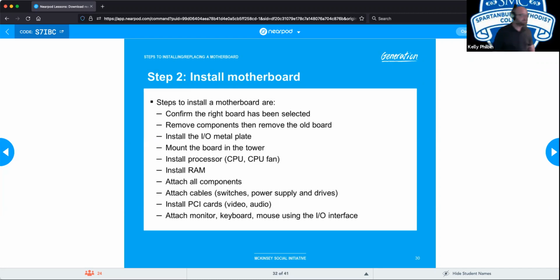All right, so once you put the motherboard back in after you remove the old one, make sure you line up all your screw holes, and then you're going to screw down the motherboard gently using a cross pattern. You're never going to go clockwise through all the screws. You're going to start at one, then go to the one exactly opposite from it, and then move in an X pattern. That way you don't over tighten one side so the board is cockeyed, and then when you screw down the other side, you could bend or break the board. This allows for even pressure to be applied and the most secure way of putting it in.